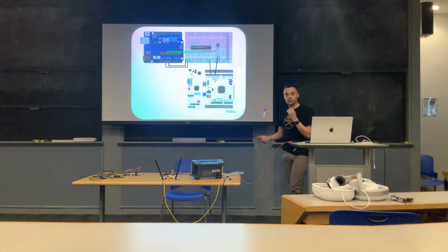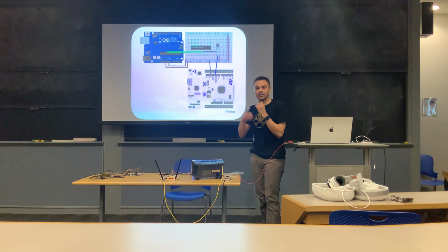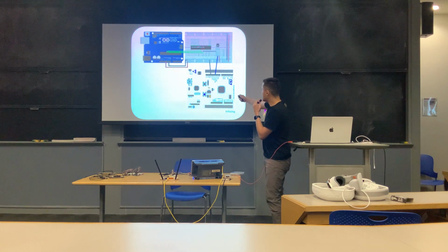Now why would I do that? Well, this way we get access to all the pins. So we can do weird things like inject faults to the clock, which you're not supposed to do. So we have the microcontroller just taken out, but it's still an Arduino. This chip has been removed, and all the pins that you need to power the chip are connected.